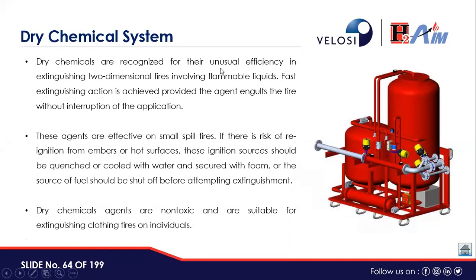Dry chemicals are recognized for their unusual efficiency in extinguishing two-dimensional fire involving flammable liquid. Fast extinguishing action is achieved provided the agent is used by the user effectively. These agents are effective on smaller spill fires. If there is a risk of reignition from embers or hot surfaces, these ignition sources should be quenched or cooled with water subsequently. Dry chemical agents are non-toxic and are suitable for extinguishing clothing fires of individuals as well.